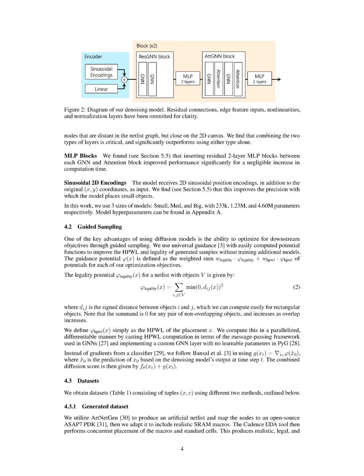Section Summary. In this section, we evaluate generated placements using legality and half-perimeter wire length (HPWL) metrics. Legality ensures objects do not overlap and are within canvas bounds, while HPWL approximates chip performance. We aim to create legal placements with minimal HPWL to optimize for downstream tasks like routing.